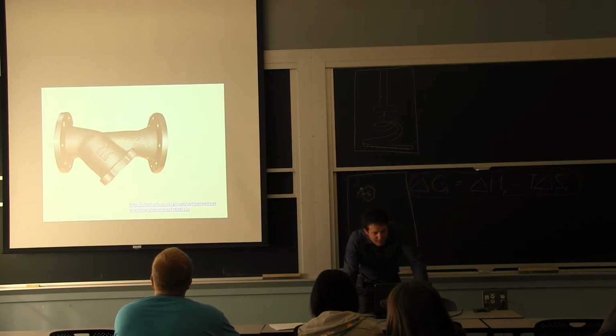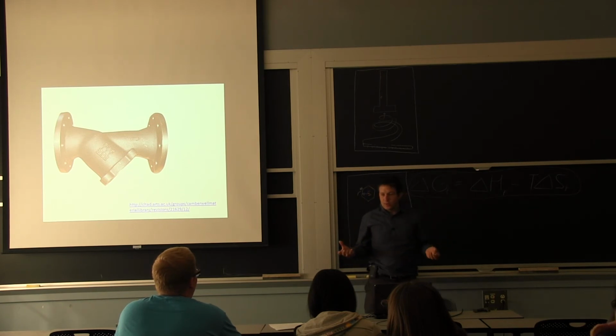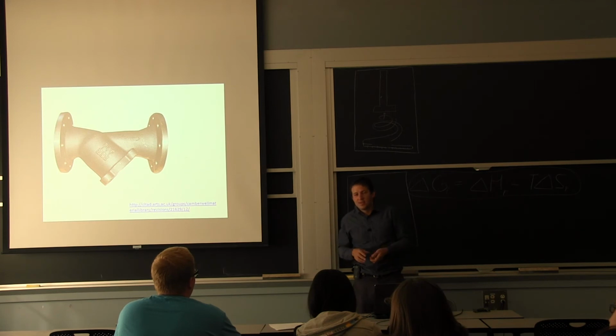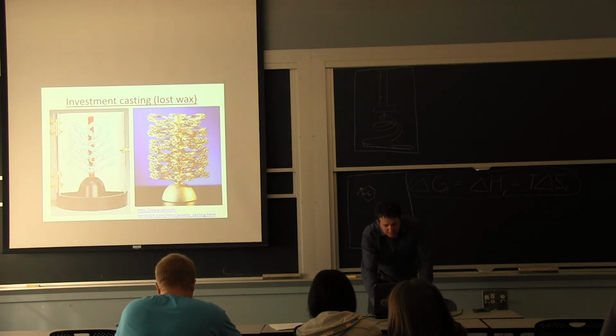And this example I picked because you can see that the flanges are being machined, so you get a good fit at those locations. It's very typical. You go to Home Depot or Lowe's, you look at the fittings, and you can say, oh yeah, it's a little rough. It's a casting surface, and then you have the machined thread coming into it because cast threads will not give you a good fit. It will not give you the best properties either. So that's essentially what I wanted to say here about sand casting.